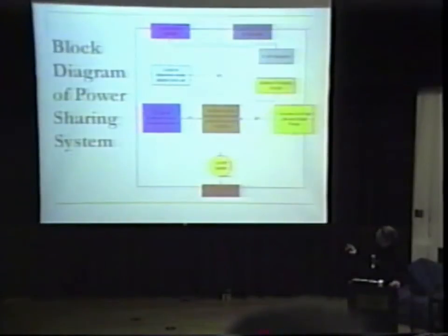The battery, there was a battery charging circuit, which, when the battery dropped below a certain voltage, would connect back to the battery and recharge it from the fuel cell. And then there was a circuit to determine when the battery runs the car, when the solar panel and fuel cell voltage drop. And finally, there was a circuit to determine when the fuel cell runs the car, based on when the solar panel voltage would drop below a certain threshold voltage.